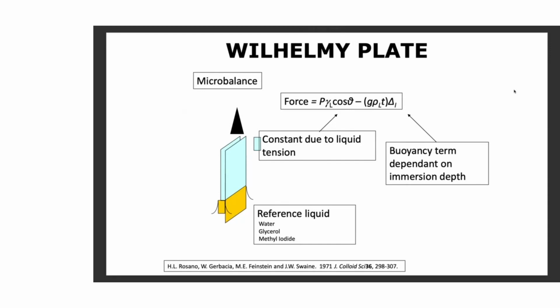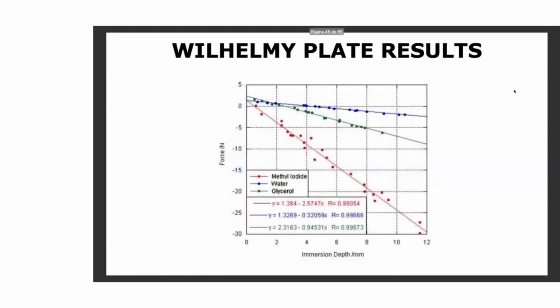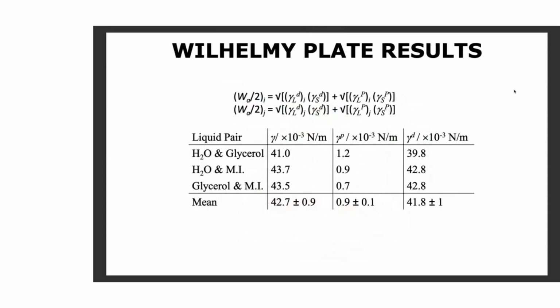You can then go and do that versus these plates covered with the binder and get the result of the surface energy that the binder coated glass plates are experiencing. This means that we can then look at what's called the pair terms between the different liquids. You can look these up. You can find out what the difference in the surface energy is between the two. So you have to use a range of liquids and then cross compare between them.